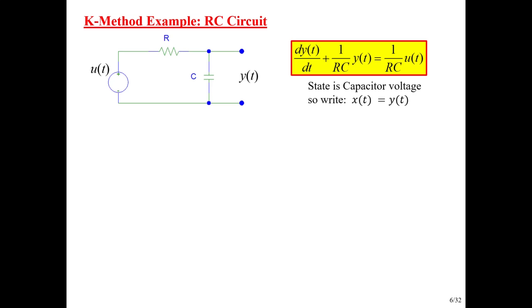So let's apply this to a simple circuit. So here's our RC circuit, the simplest circuit that we might encounter in a real-world application. Now, remember when I was saying make sure you model the impact of the output impedance of the driving stage and the input impedance of the driven stage? So I'm not showing that here. If I were, I would need to put another resistor here. We'll call it R sub O.